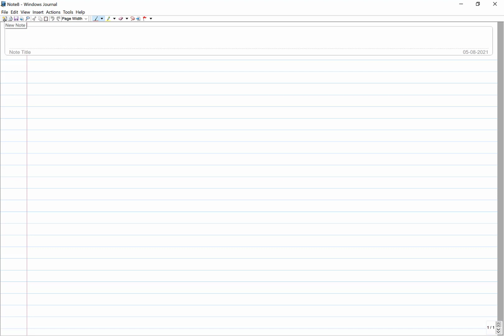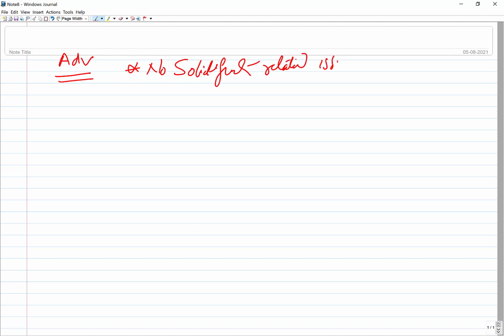Okay, coming to the advantages of the solid state joining process. Maybe about this and many other things we will talk a little later. The thing is, there are no solidification related problems in solid state joining. You have seen they are mostly deformation based, diffusion based or chemical process based. So there are no solidification related issues, which may be in the form of pores or inclusions or cracks, solidification cracks, etc.